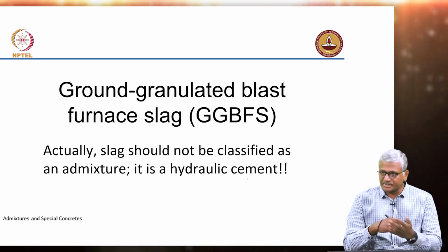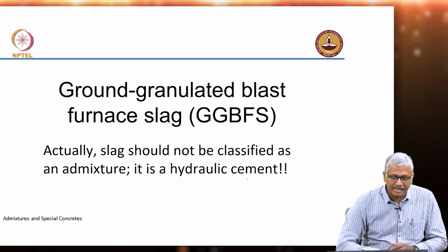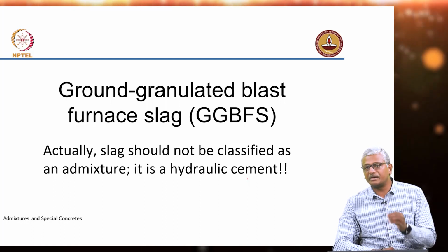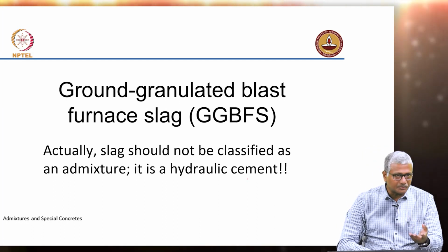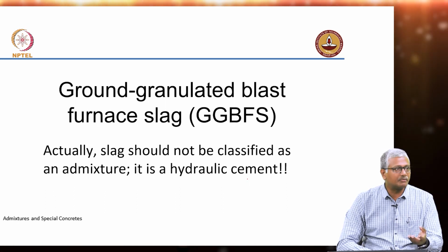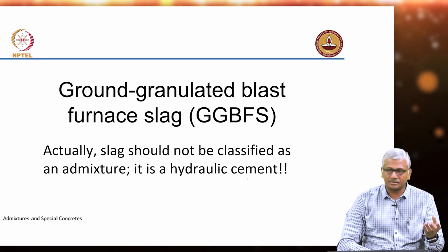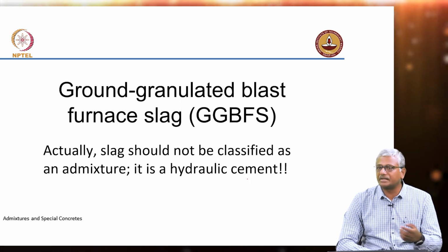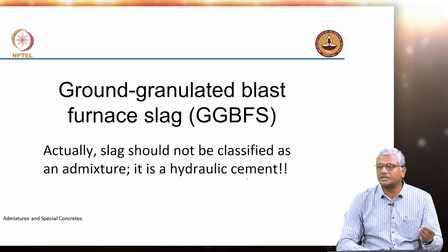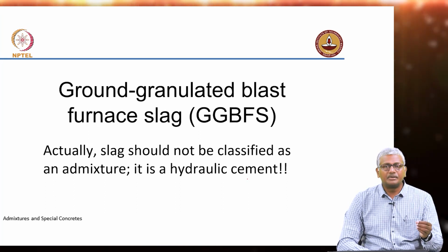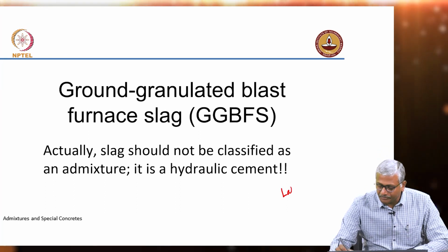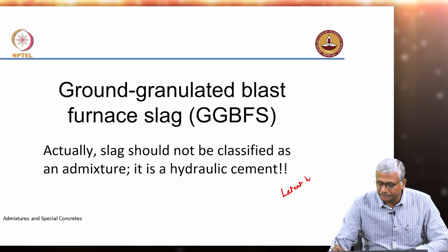So, we have discussed earlier that ground granulated blast furnace slag is not really a mineral admixture, it is a hydraulic cement on its own, because it has the potential to react with water. However, it needs some activation for the reaction. It can react on its own, but it happens very slowly, but in the presence of activators, it can actually react much faster, right. So, that is why we call it a latent hydraulic binder.